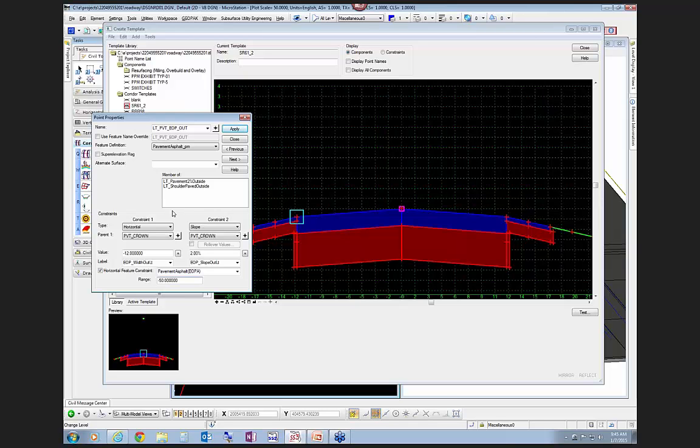If that line somehow is drawn inside of 12 feet, it's going to default to this particular width because my range isn't particularly right. If that was the situation, let's say that I needed to come down to at least 10 feet, or let's say it was an odd number, 9.69, all I'd have to do is set this horizontal width to be -9, just something inside of where that line is, and then this override would know to go from 9 to 59, and then it would actually hit it.